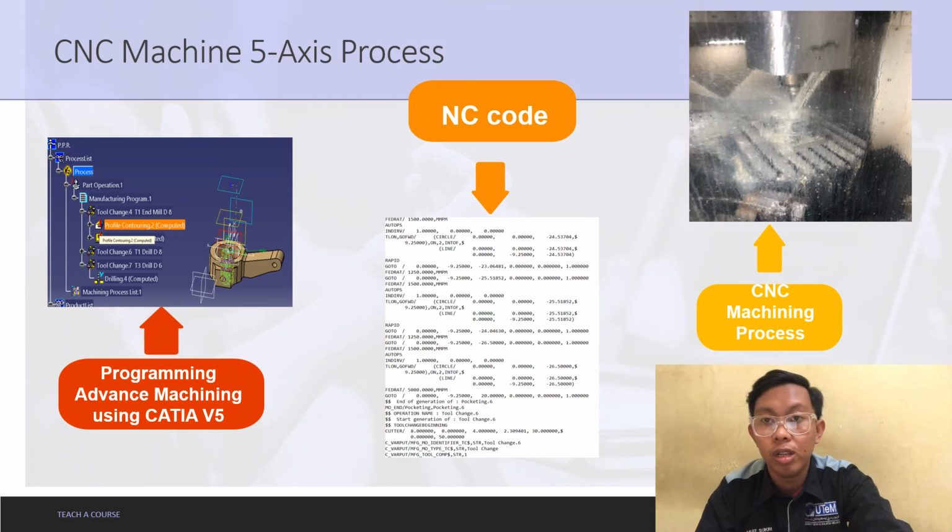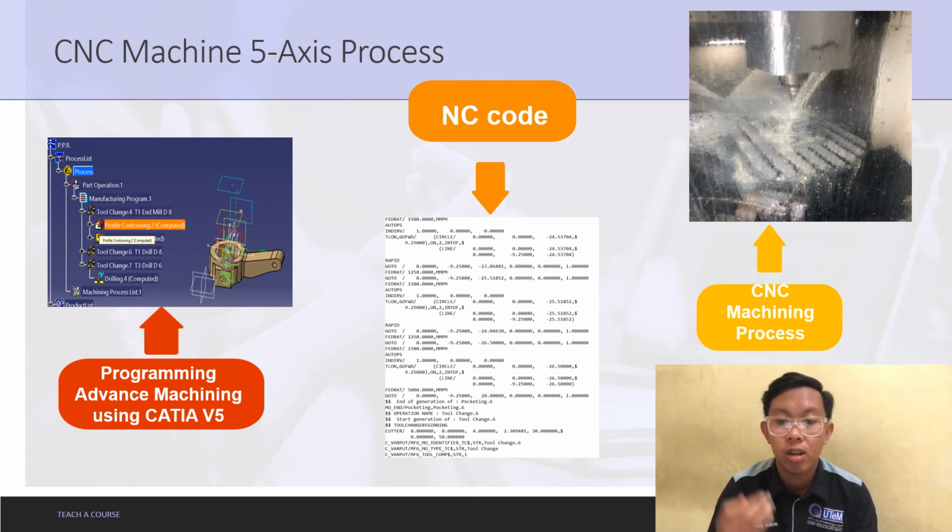We use an end mill of diameter 8, then a drilling diameter 8 and a drilling diameter 6 process as the tool points that have been employed. The profile contouring and the pocketing are the two processes that are used. After that, we drill the remaining 3 holes. So NC code was generated for the object.